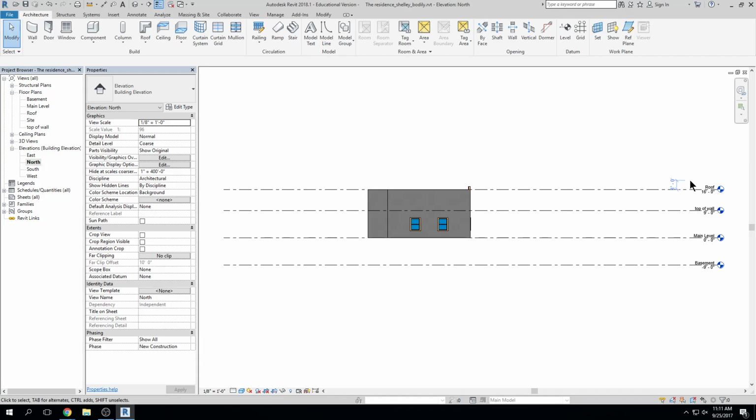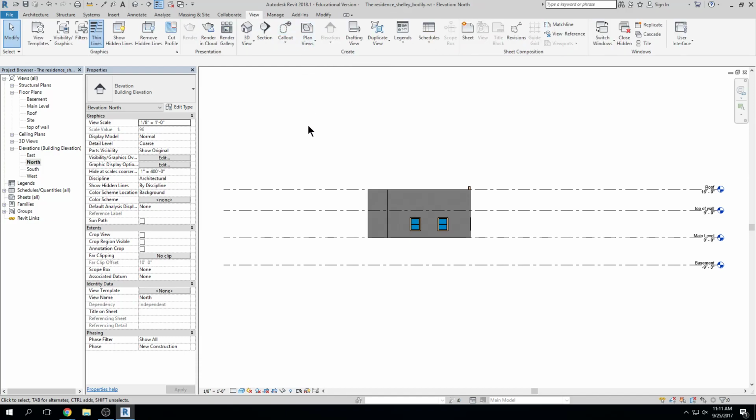Which, from maybe what you're gathering in Revit, is kind of a novel thing. We don't generally just create brand new things in Revit. Usually we take an object that's existing, we duplicate it, rename it, and redefine it. Well, we can also do that with plan views, section views, and elevation views. Instead of coming up to Level or going over to View and to the plan views, I can take an existing view and copy it. I can duplicate it, rename it, and then alter it to fit whatever I'm trying to do.